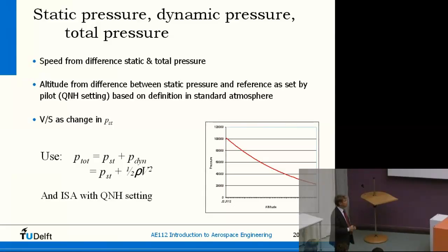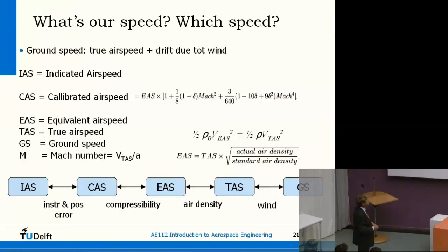During the flight, that's the main important thing, but as soon as we get lower, where there are mountains, or we want to land or take off at some point, then you need to know the pressure at sea level before you can tell what your actual altitude is. The radio altimeter only works at the very last second. You cannot use that at a few thousand feet. So the only way to do that is to know the reference level, and that is called the QNH setting. So you need to set the QNH, and then everything works for the air data computer.